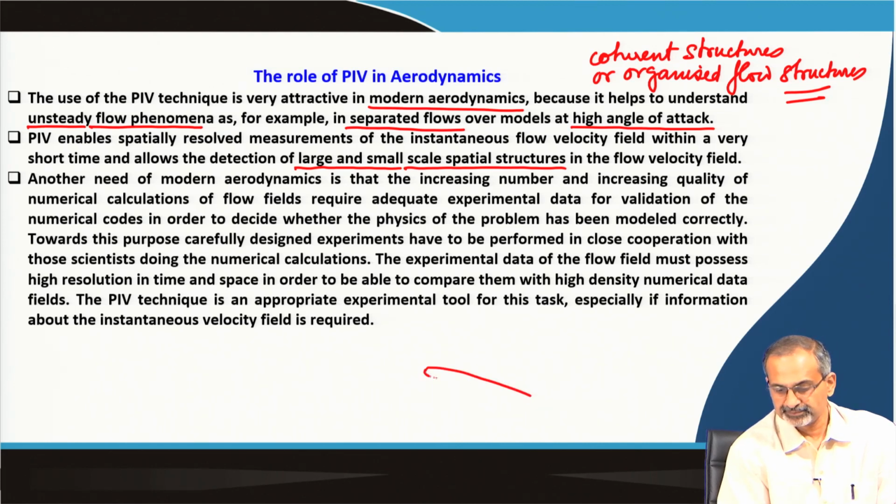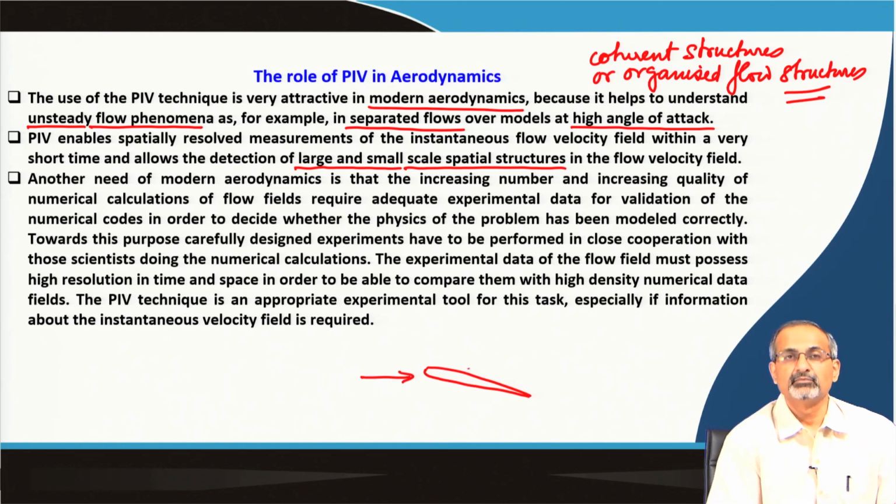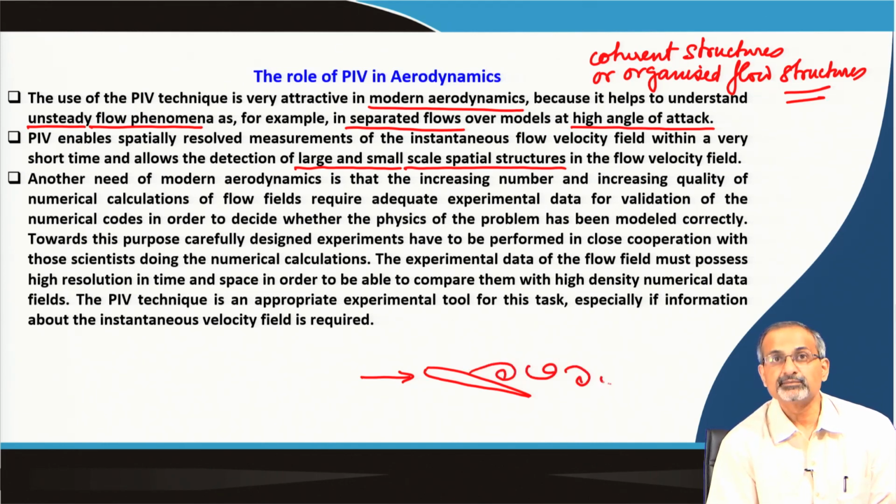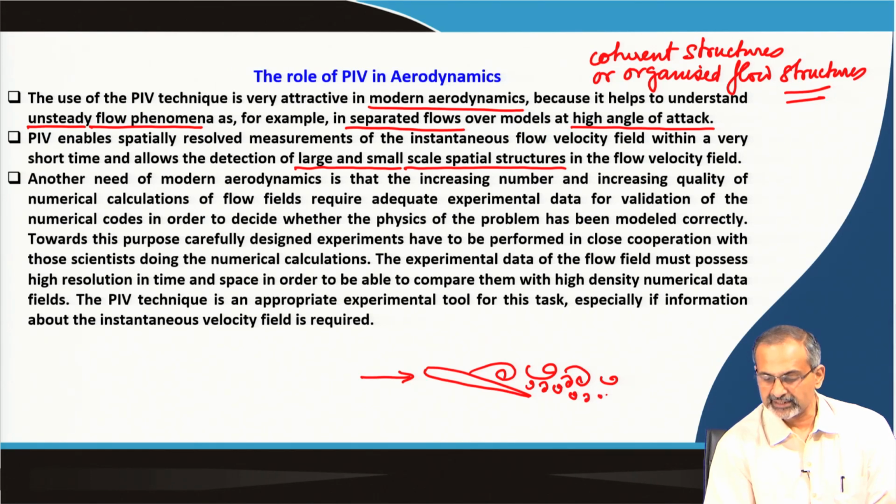For example, if you are looking at flow past an airfoil at moderate to large angles of attack, where flow separation has initiated, then large eddies are formed around the body and they convect into the wake. Additionally, these large eddies break down into moderately sized eddies and still smaller eddies, to extremely small structures. That means there are a range of scales,